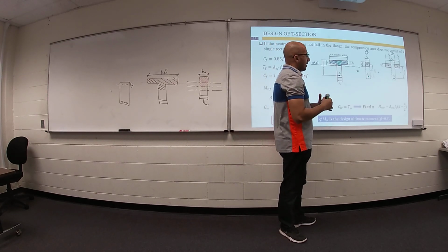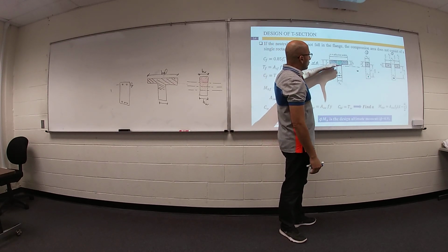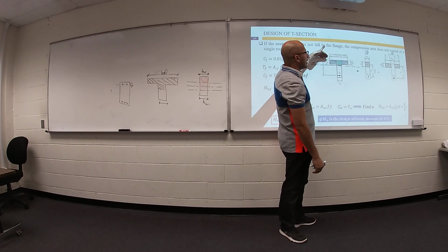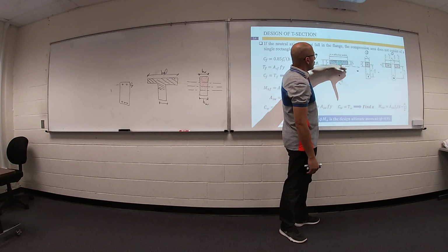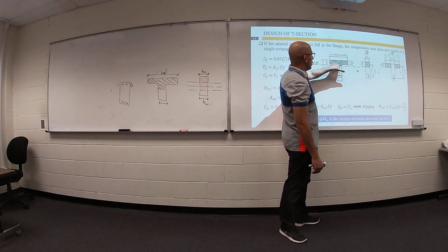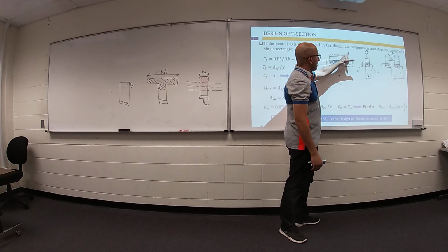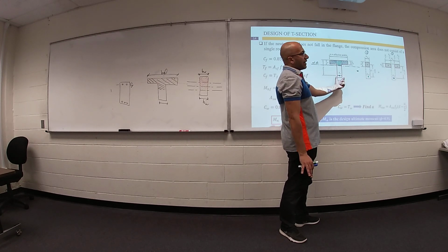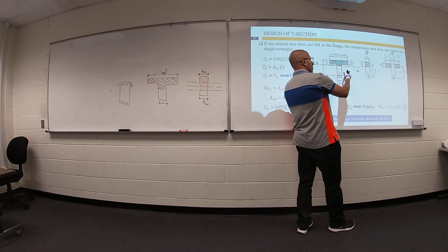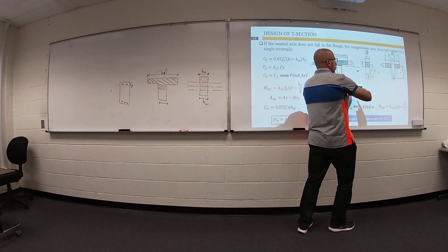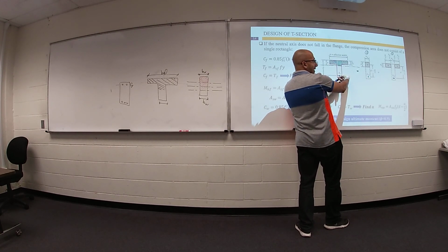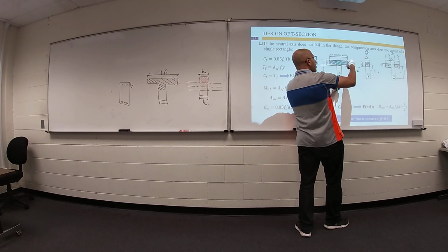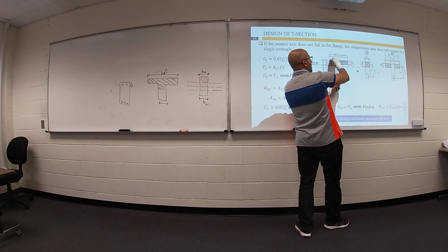One more time. Right now, my neutral axis is outside your flange. So the area under compression above your neutral axis looks like a T section. And we still have area of steel. We would like to divide this cross section into two parts. First part of your area of steel will work with these shapes of flange.